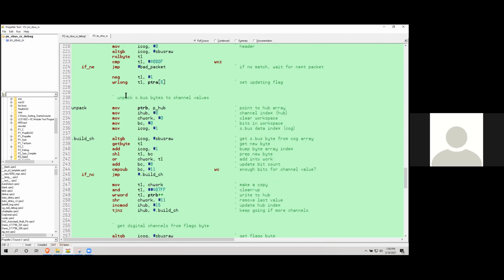I had started with something because I found, after I'd already gotten heavily into this, that Jason Dory had written an SBUS receiver for the P1. His unpacking algorithm counted on the bytes being reversed, being flipped bit order. I started that way, and then after finally absorbing it, found that I don't need to flip the bytes.